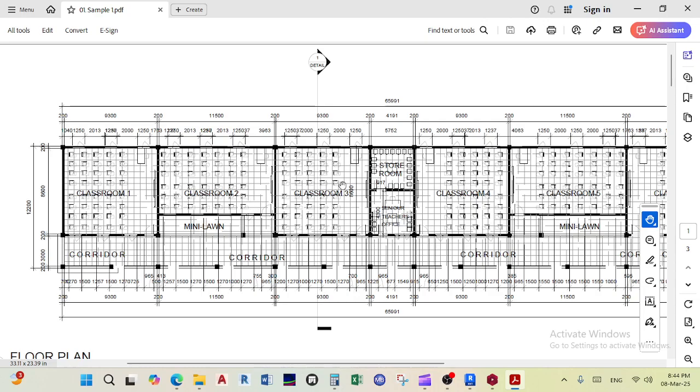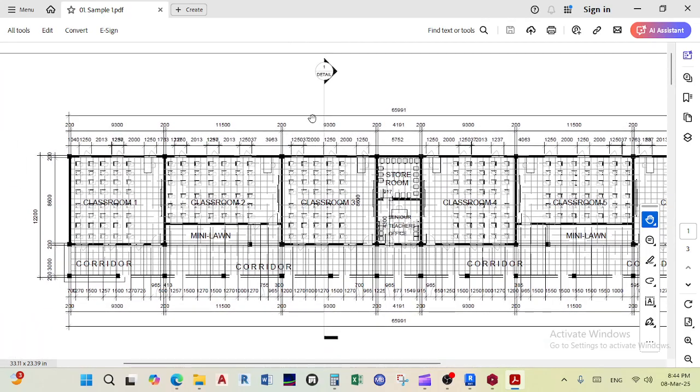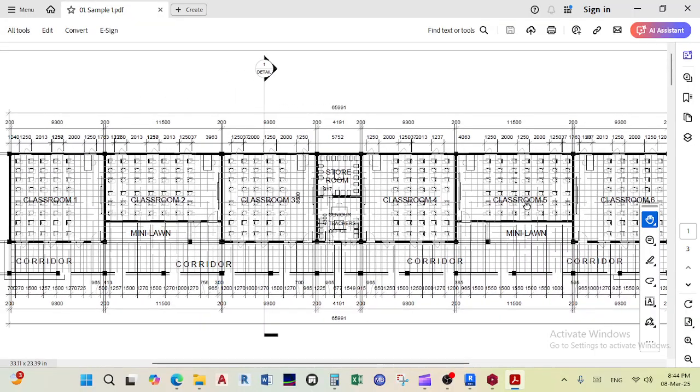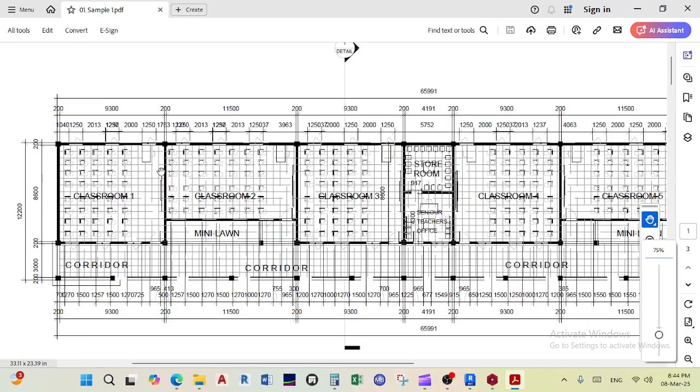So obviously there'll be stops, you need to carry out some quality control, you need to sample some cubes. So you are very likely to have construction joints in here. Or when you finish this slab, you need to cut certain sections. It's called a saw cut joint.